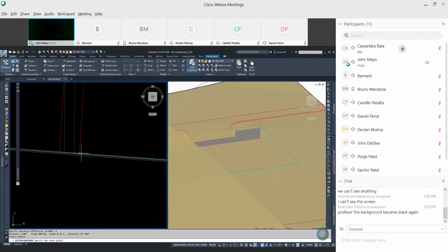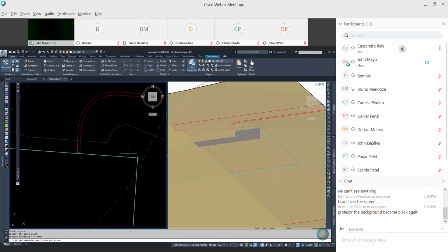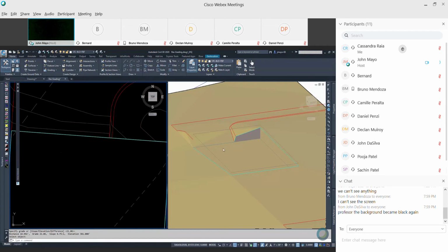And now I'm just going to check my slope up through here. Look at that, the grade is 21. If you remember, I told you the maximum grade you're allowed is 1 on 3 rise over run, which turns out to be 33.33%. So my grade line works. This is less than the maximum slope.